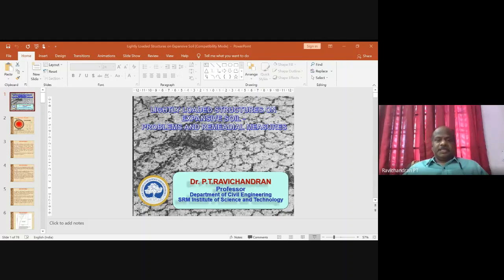So what is expansive soil? Generally, there is a considerable swell because of the absorption of water from outside, and it may sink after the removal of the water due to evaporation or some other causes. This phenomenon occurs to some extent in clay soil, except sandy soil, but it exhibits a very high degree in certain clay soils. Hence, such soils are called expansive soils. This soil is one of the most problematic for geotechnical engineers.